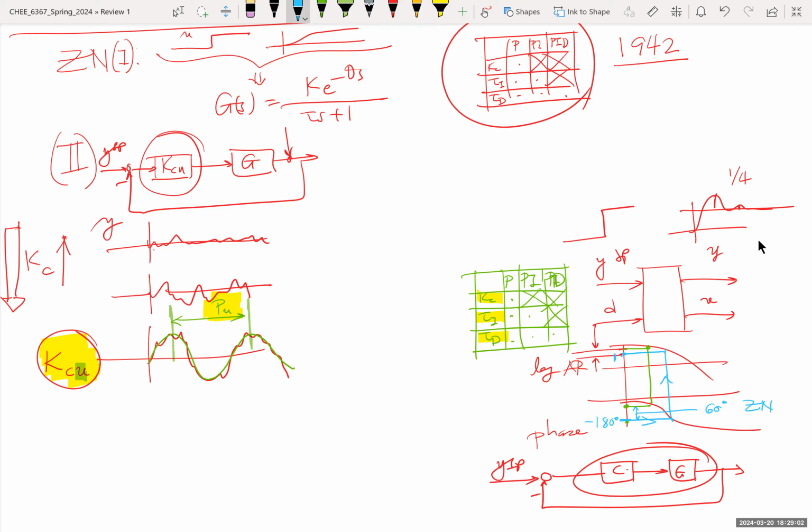And so there was beautiful theory, nicely theoretically analyzed by Ziegler and Nichols. And it's interesting to understand these things, but we want to go quickly because we don't want to turn this into a math course. Okay? But it's useful to know qualitatively what Ziegler and Nichols buys you. It's not just, well, here's a table, use it, done. Here's a table, use it, and understand that you may have to modify it, using the theory, for example, for faster closed loop response, increase the gain, to improve robustness, decrease the gain, things like that.